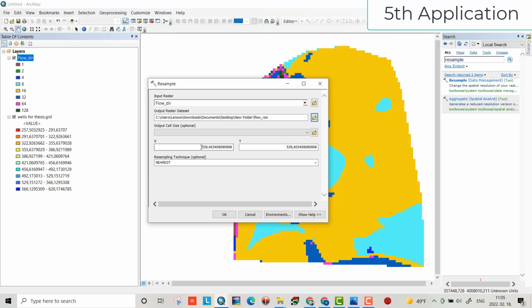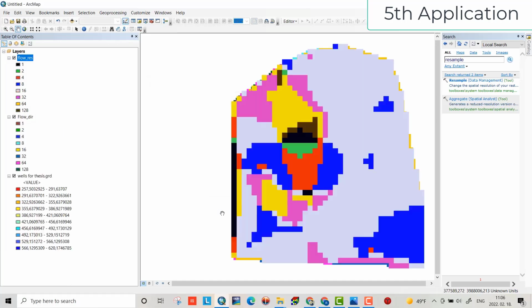And here you can determine the size of your cells, the output cell size. Because my area is large, about 3000 square kilometers for me, I use this large number, 1250. Okay, then we have to change the file to points.